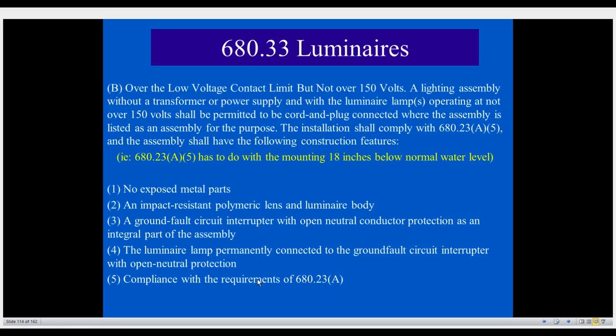Now, the reference back to 680.23(A) is just saying, look, there are some requirements for the lighting design and the normal operation that you have to follow for general underwater luminaires. We've got to follow that. You do have some aspects dealing with the transformers and power supplies, GFCI protection. You have the voltage limitations which are going to apply, which is the 150 volts between conductors, and all that type of application.